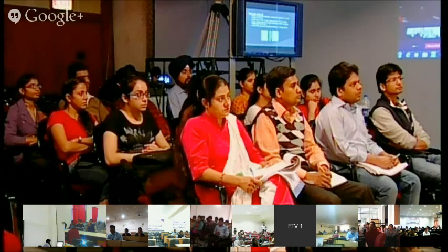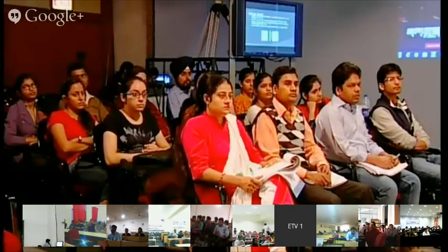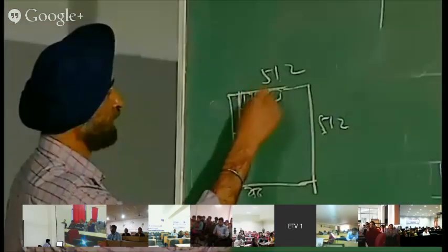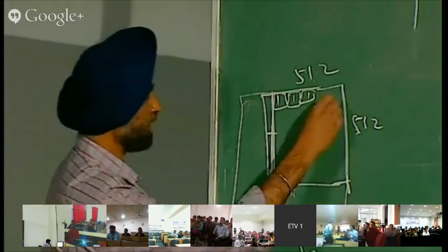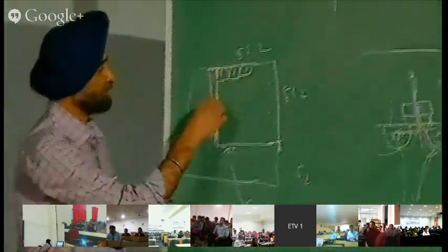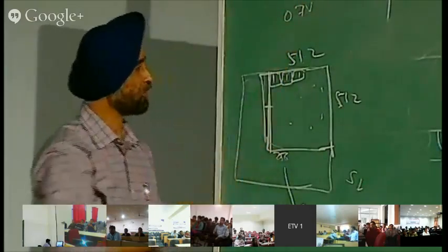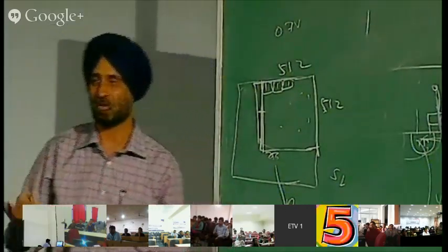So in a memory, this is the memory logic, the memory cell. Here you have cells like this, 512 cells, where one bit is stored. Then this is the peripheral circuit. So this is an SRAM. Some data is stored in this cell. This is the peripheral, which is a row decoder, column decoder, sense amplifier. Now in this, you cannot reduce the voltage below say 0.7 volts, because if you reduce the VDD of these memory cells beyond 0.7 volts, the data will be lost.